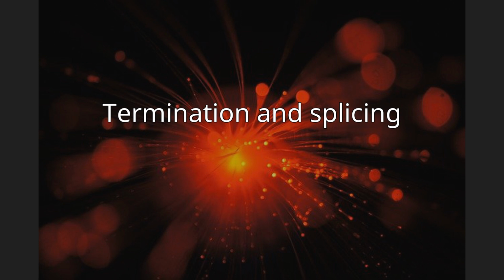Fibers are terminated in connectors that hold the fiber end precisely and securely. A fiber-optic connector is basically a rigid cylindrical barrel surrounded by a sleeve that holds the barrel in its mating socket. The mating mechanism can be push and click, turn and latch (bayonet mount), or screw-in (threaded). The barrel is typically free to move within the sleeve and may have a key that prevents the barrel and fiber from rotating as the connectors are mated.